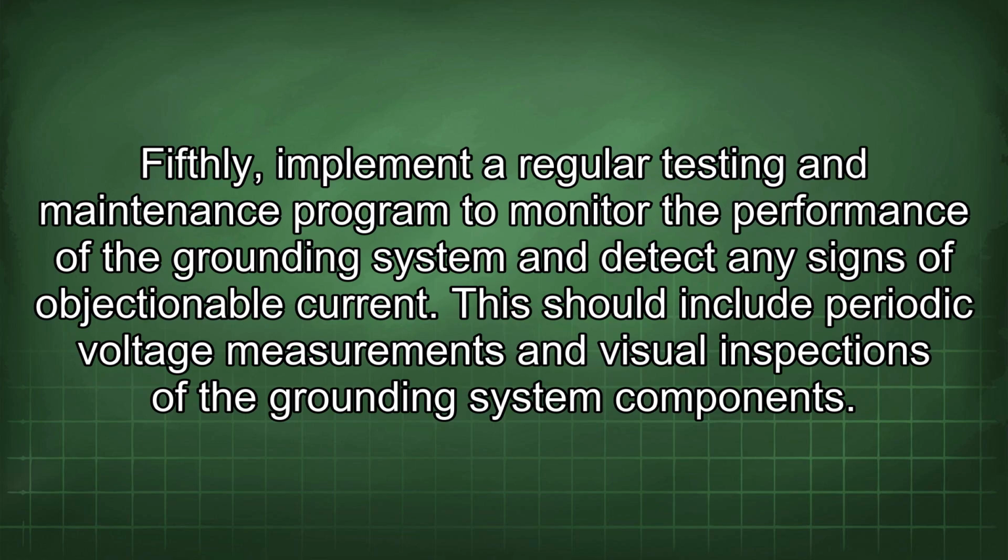Fifthly, implement a regular testing and maintenance program to monitor the performance of the grounding system and detect any signs of objectionable current. This should include periodic voltage measurements and visual inspections of the grounding system components.